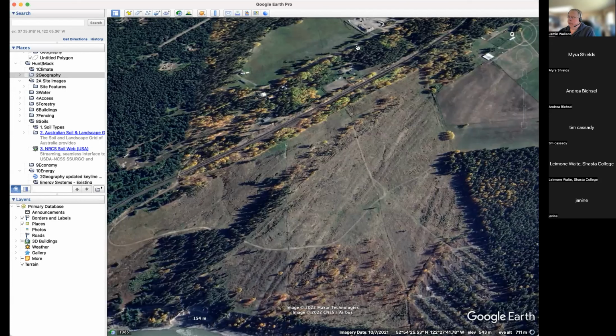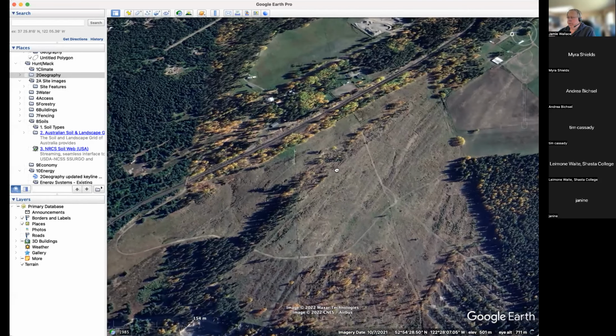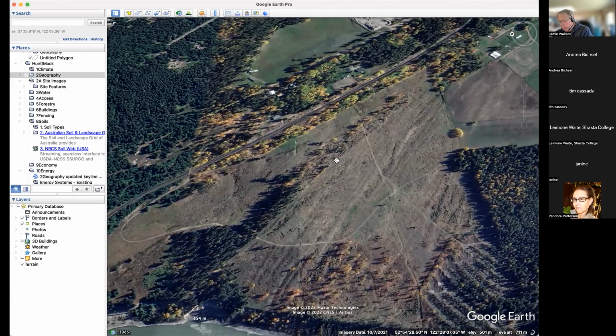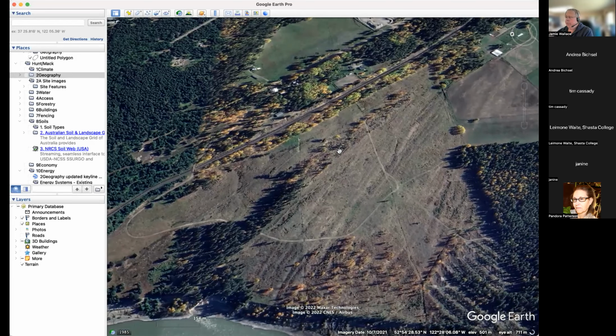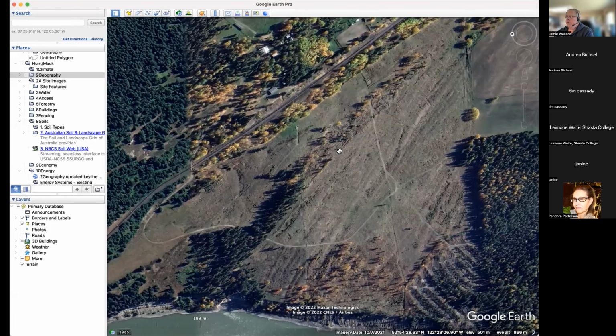In some ways I like this angle for this site, but the easiest thing to do in Google Earth Pro is, if you get pretty close to where you want to be, you hit the U key, and that takes you directly to a 2D overhead view. That's what you want to do when you're taking a screenshot. You want to be directly overhead, and that way any scaling is accurate, whether it be at the top or the bottom of the image.